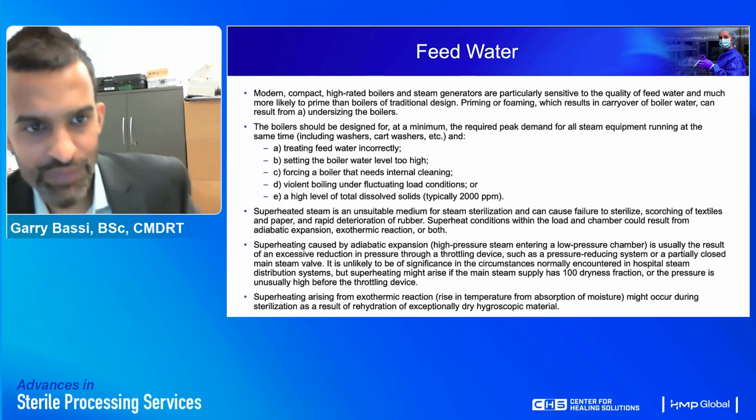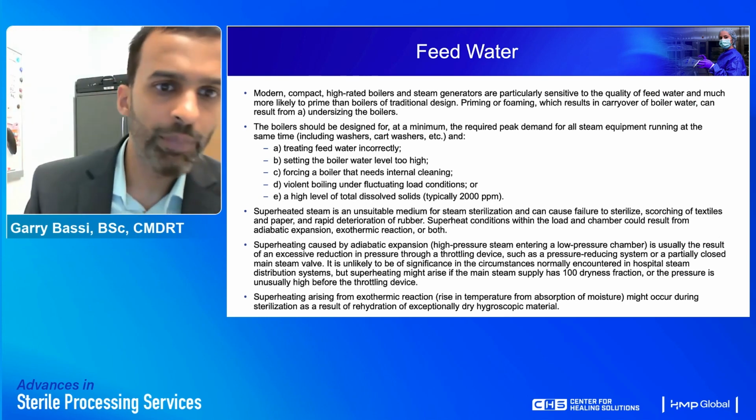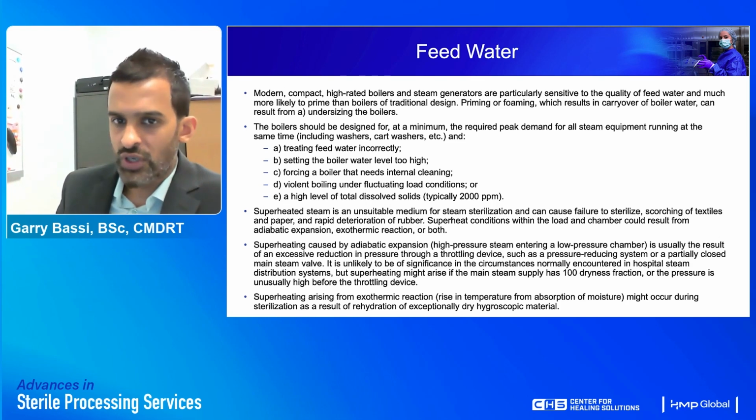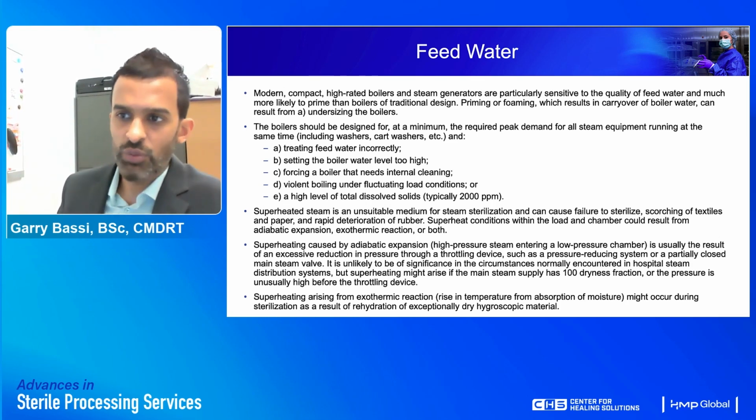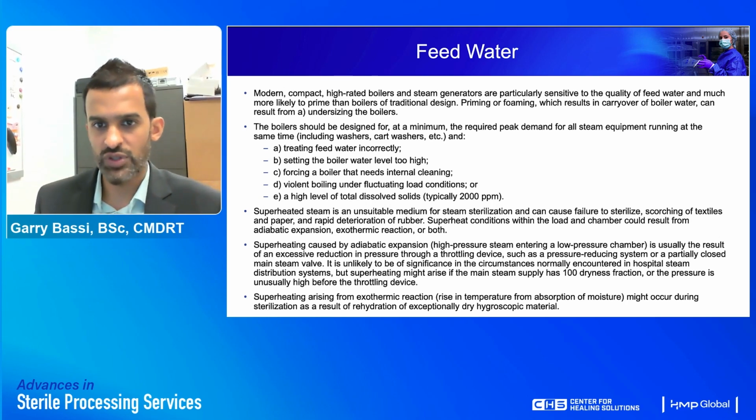Next slide, we're going to talk about feed water. So the feed water that the steam is generated from. The modern compact high-rated boilers and steam generators are particularly sensitive to the quality of feed water and much more likely to prime than boilers of traditional design.